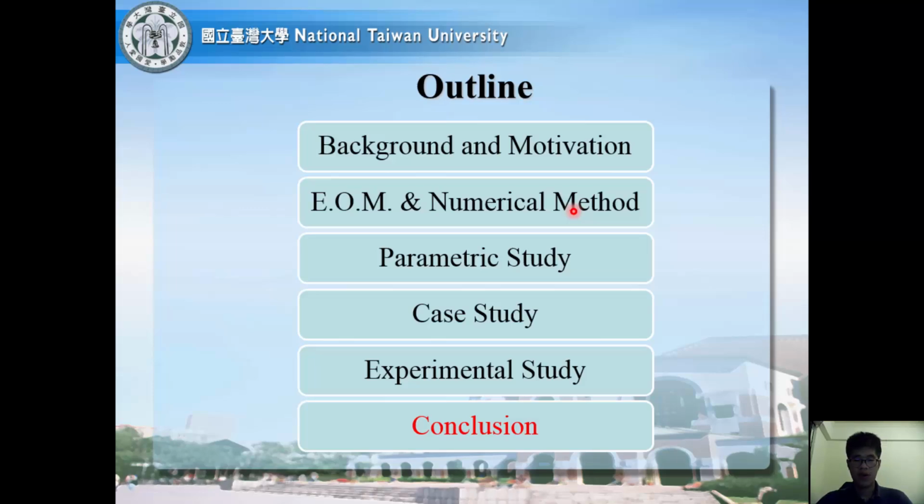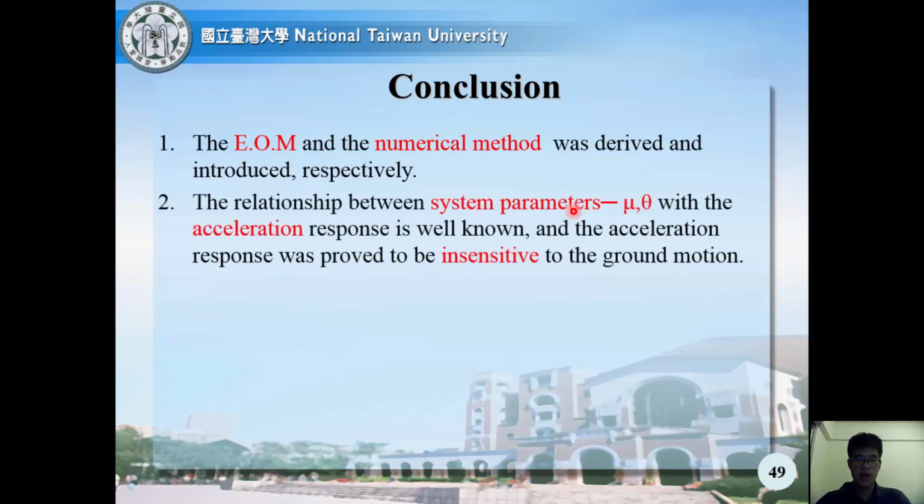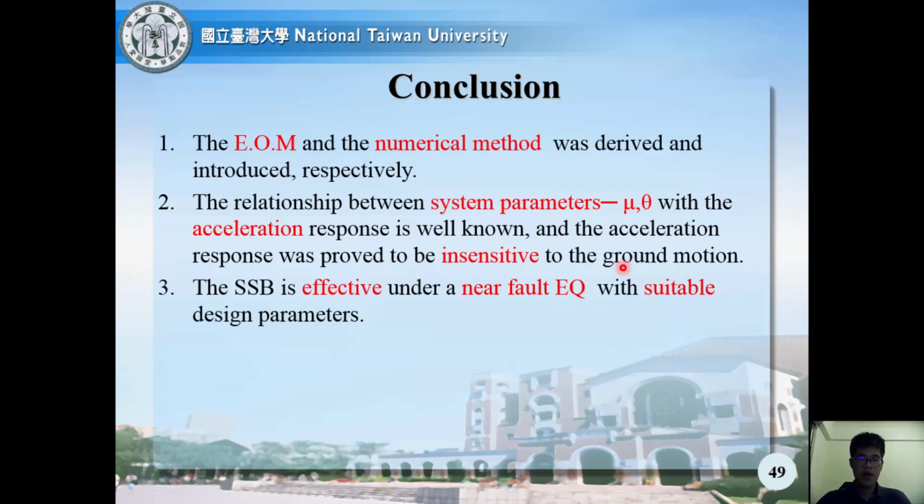The last part will be my conclusion. First of all, the equation of motion and the numerical method were derived and introduced respectively. Second, the relationship between the system parameters, which are the friction coefficient and the inclination angle, and the acceleration response is well known, and the acceleration response was proved to be insensitive to the ground motion. Third, the SSB is effective under a near-fault earthquake with suitable design parameters.